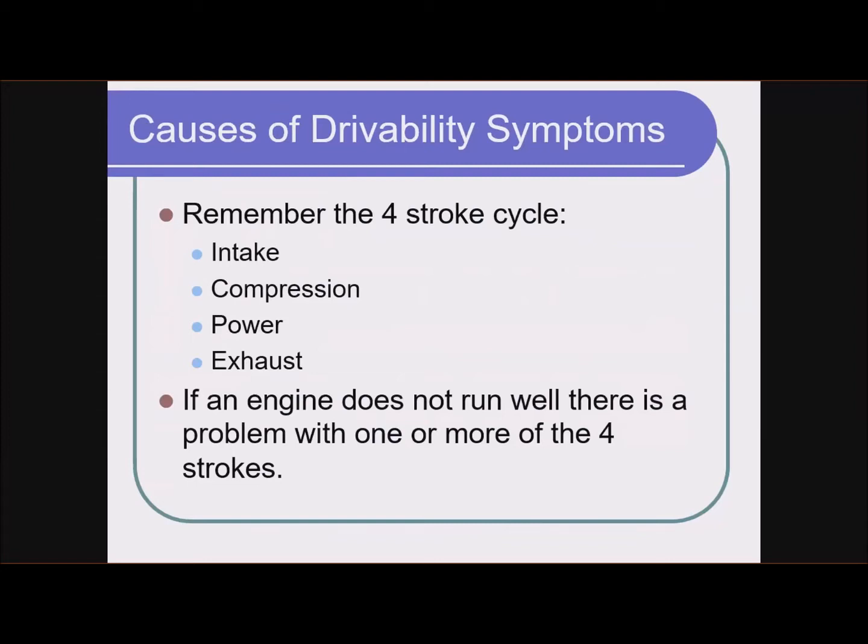Plugged exhaust. In the lab, you didn't all get to see it, but some of you, we did the exhaust back pressure test on a Ford Escape. We pulled the oxygen sensor out, put a back pressure gauge in its place, ran the engine at idle, ran it at 2,500 RPM, and then using rags stuffed into the tailpipes, tried to increase the exhaust back pressure and see what it does on the gauge. So if the engine can't get rid of its exhaust, it can't take in more air. So that's going to definitely limit how fast the engine can run.